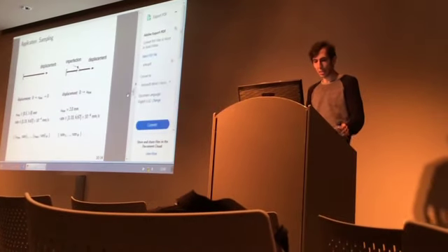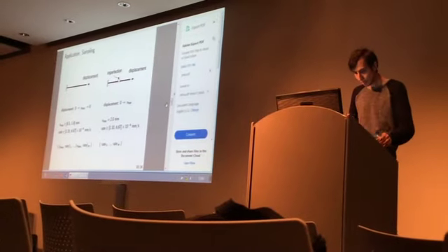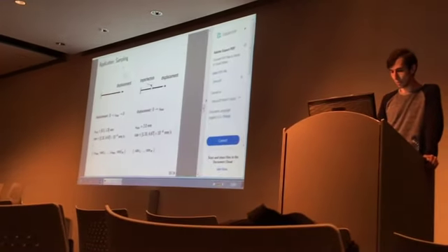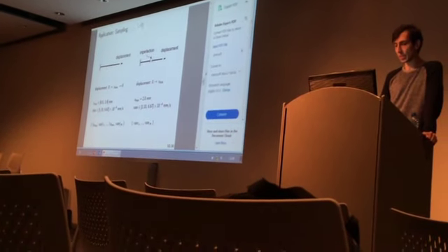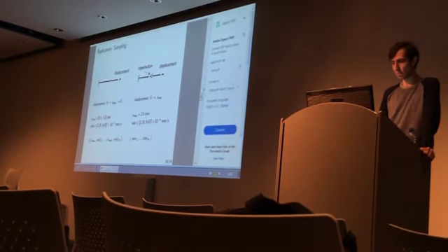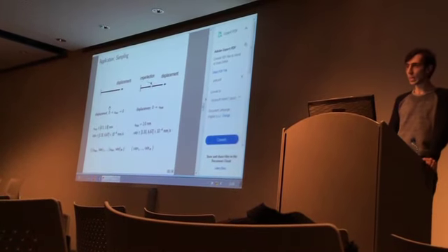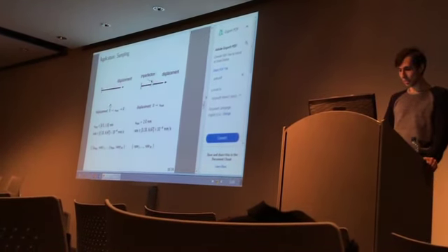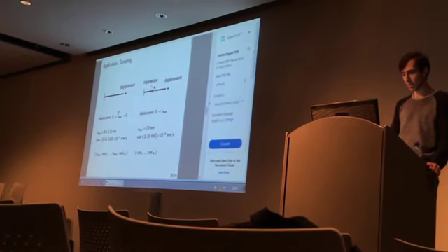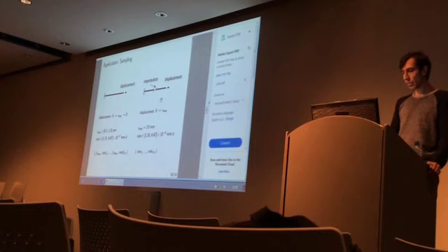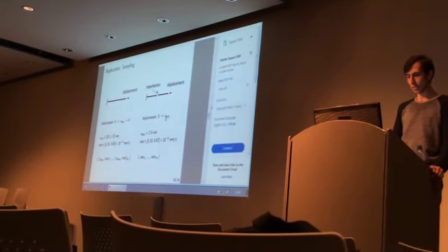Now, let me tell you how I do the sampling. I consider two macro models, one a bar without imperfection and the other one a bar with imperfection. For the bar without imperfection, I pull one end of it until it reaches a value of U max, and then push it back until it goes where it was. For the bar with imperfection, I would just pull it until it reaches a value of U max.